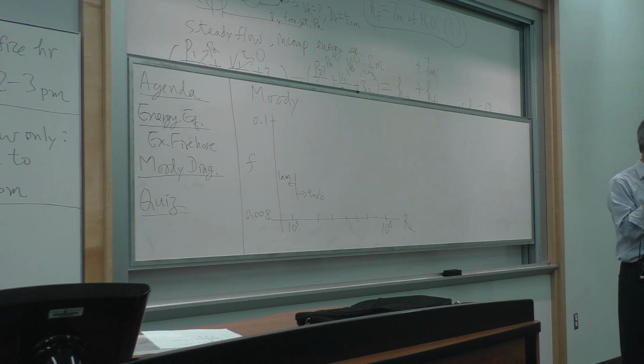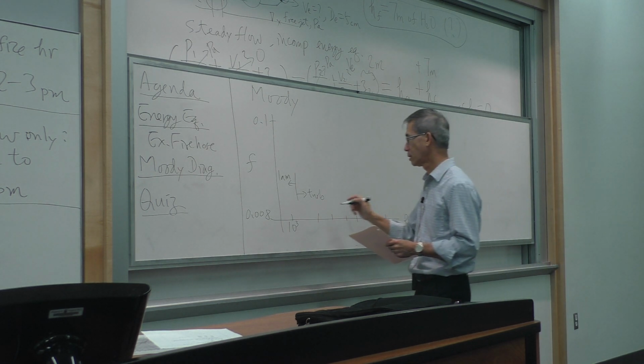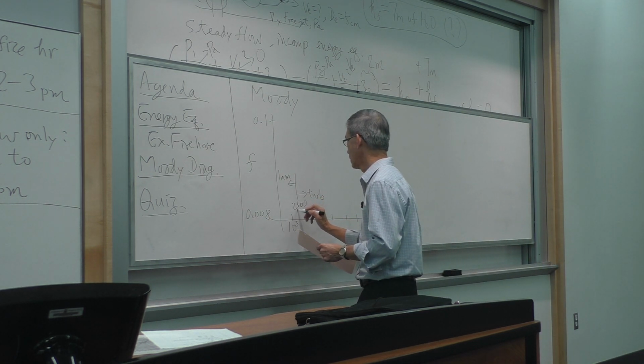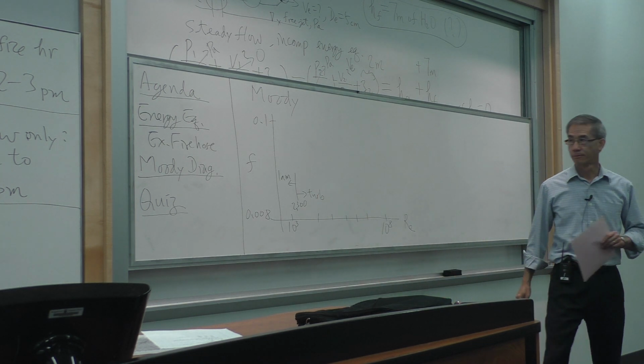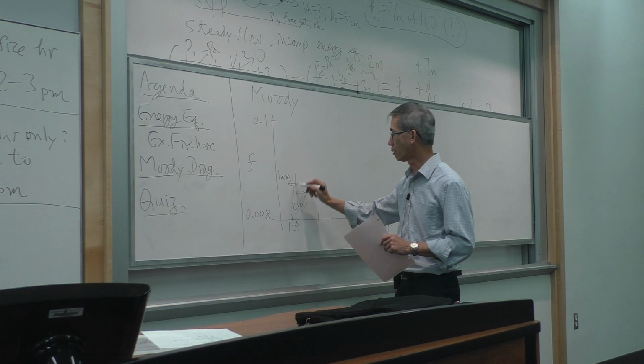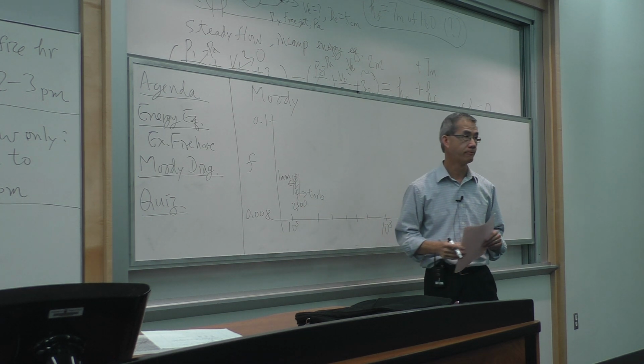So we have talked about this naming of the turbulent transition at approximately what Reynolds number? 2300, and that's academic. Anything from 1,000 to 4,000 is acceptable. So this is not an on-off type transition from laminar to turbulent, it's a gray area.